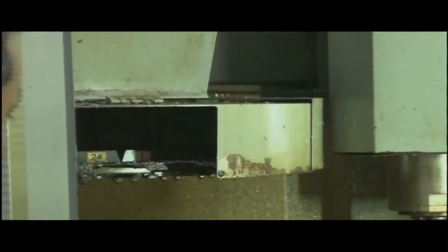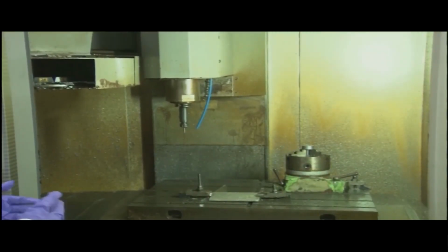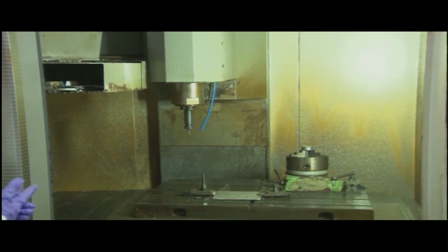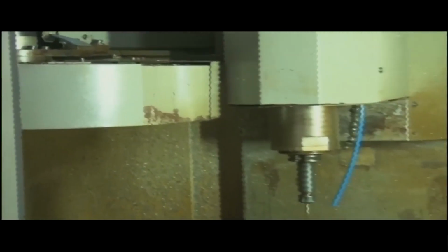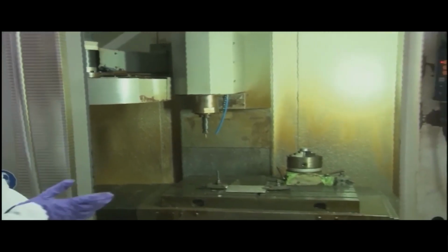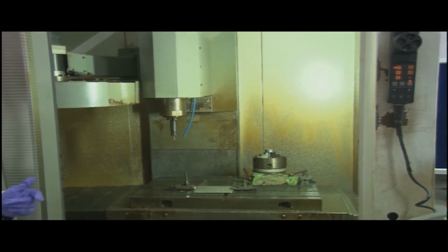In this we have this turret as well. This is also known as the tool magazine. It can hold a number of tools, it can hold 24 tools, and these tools can be changed while working. As you know, M is miscellaneous command, M6 is the tool changing command. We can put the tool number, like T4 M6. The tool at the 4th number in the magazine would be taken up, and this can be done in the program itself. The machine can keep changing the tools while it is working. Like it can do a roughing operation in the beginning, then it can pick a profiling tool, then it can pick a ball mill, another finishing tool, and do the whole operation in one go. So, this is the beauty of the CNC machine.